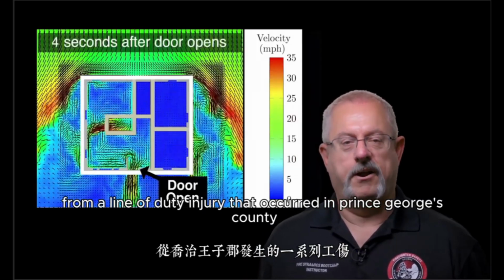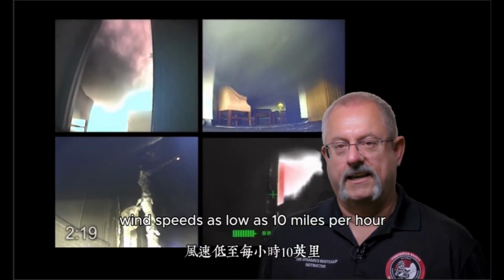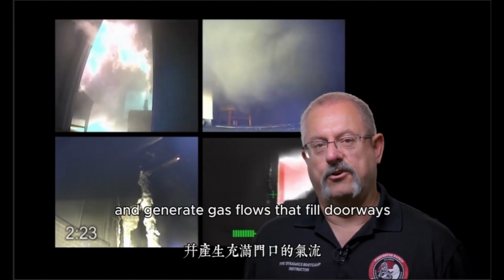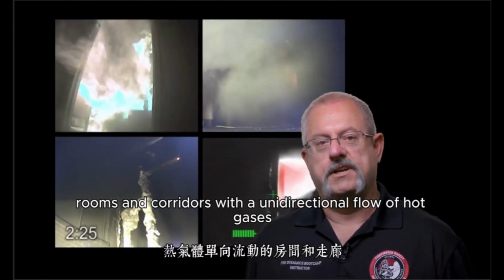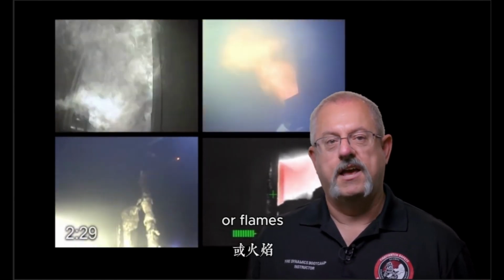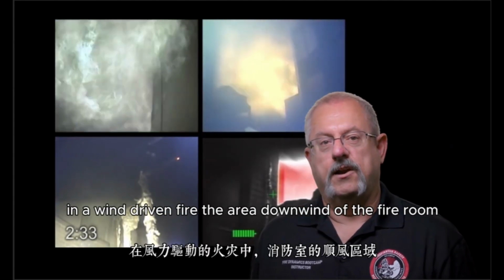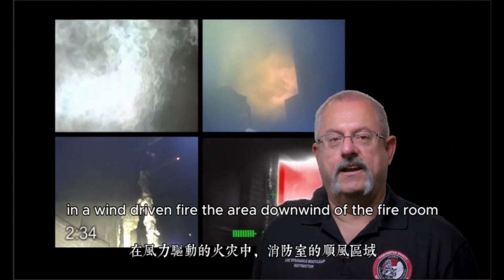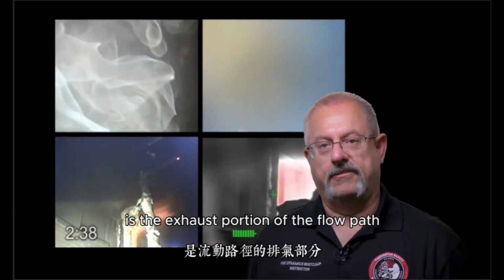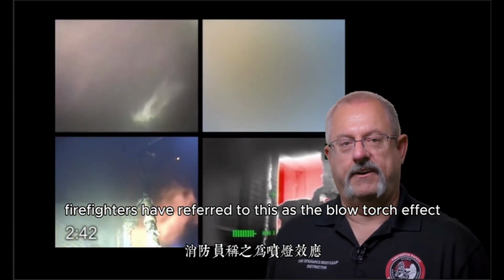Wind speeds as low as 10 miles per hour can increase the heat release rate of the fire and generate gas flows that fill doorways, rooms, and corridors with a unidirectional flow of hot gases or flames that can extend from the ceiling all the way down to the floor. In a wind-driven fire, the area downwind of the fire room is the exhaust portion of the flow path. Firefighters have referred to this as the blowtorch effect.